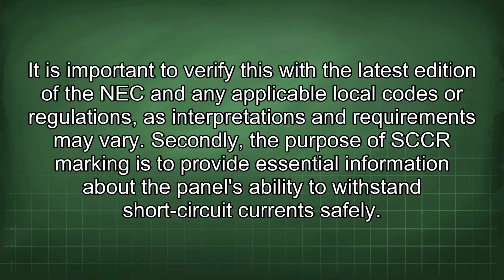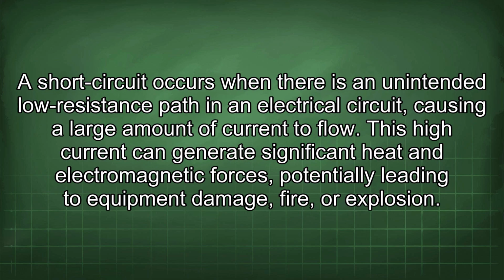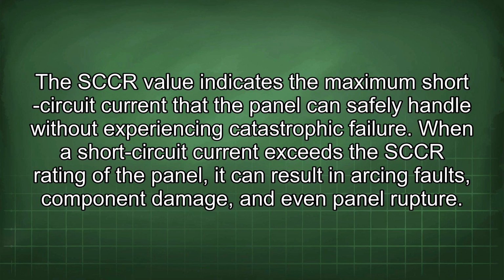Secondly, the purpose of SCCR marking is to provide essential information about the panel's ability to withstand short-circuit current safely. A short circuit occurs when there is an unintended low resistance path in an electrical circuit, causing a large amount of current to flow. This high current can generate significant heat and electromagnetic forces, potentially leading to equipment damage, fire, or explosion. The SCCR value indicates the maximum short-circuit current that the panel can safely handle without experiencing catastrophic failure.